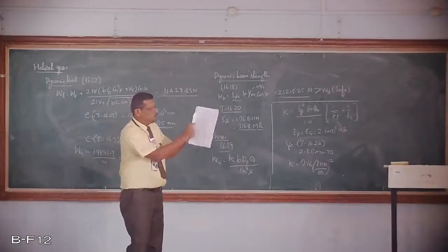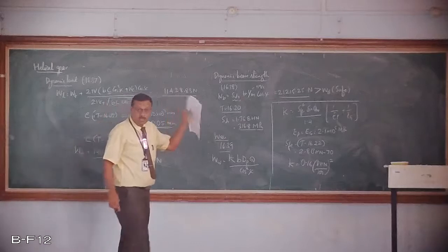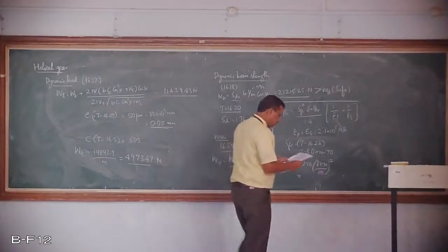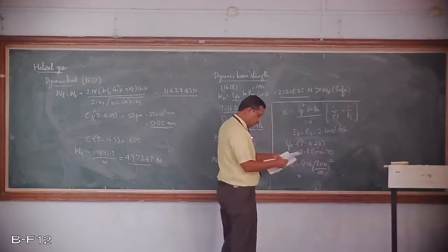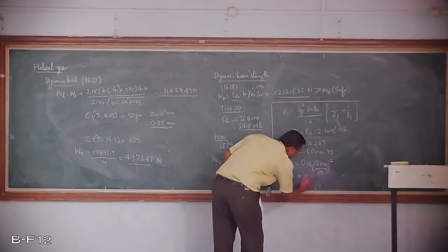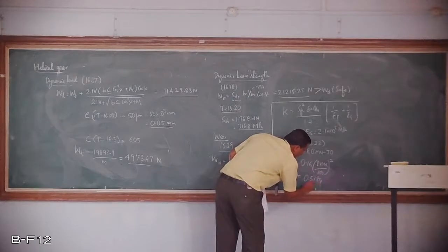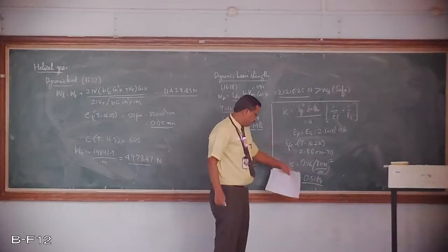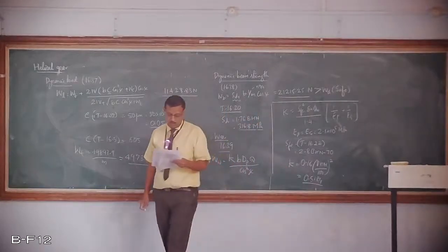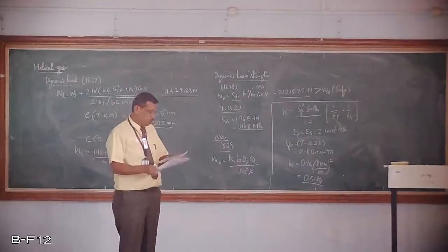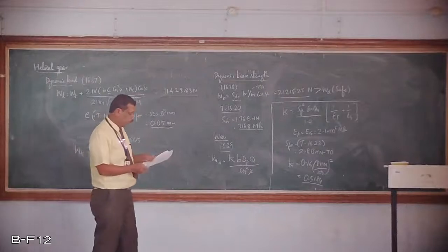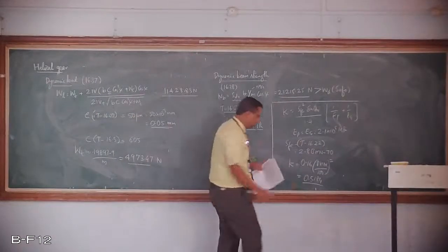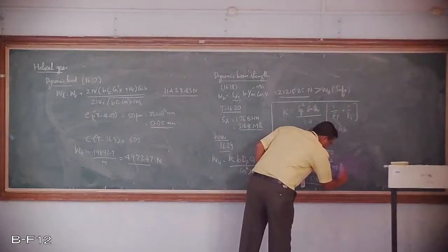Therefore, let me substitute the value of BHN of the gear. If you substitute the BHN of the gear, that is 180, we are going to get the value of K as 0.5184. Therefore, K can be obtained by different methods: one by the table, and second by this equation given in the data handbook. I am making use of equation 16.39, given on page number 221.